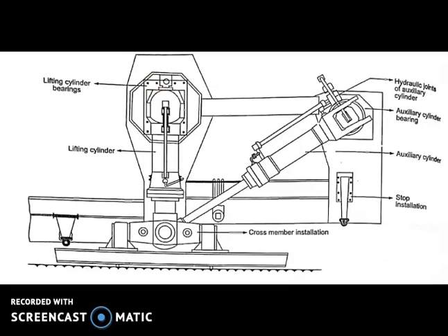The links are connected on the shoes and eccentrics are in a lifted position. A and B are the pin points of the eccentric and shoe with the link. As the shaft rotates by 90 degrees, the points A and B shift accordingly, vertically and horizontally. This results in a sweep of the shoe in the following way. A vertical sweep helps the shoe to touch the ground, while a horizontal sweep brings the shoe to the new position.